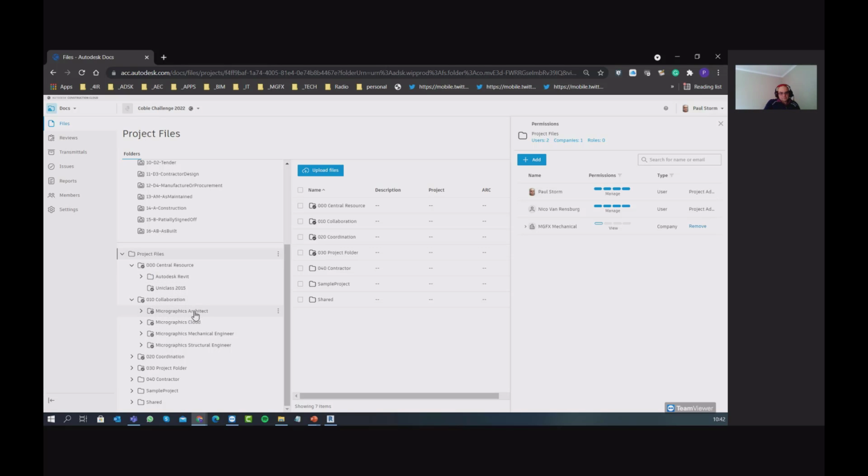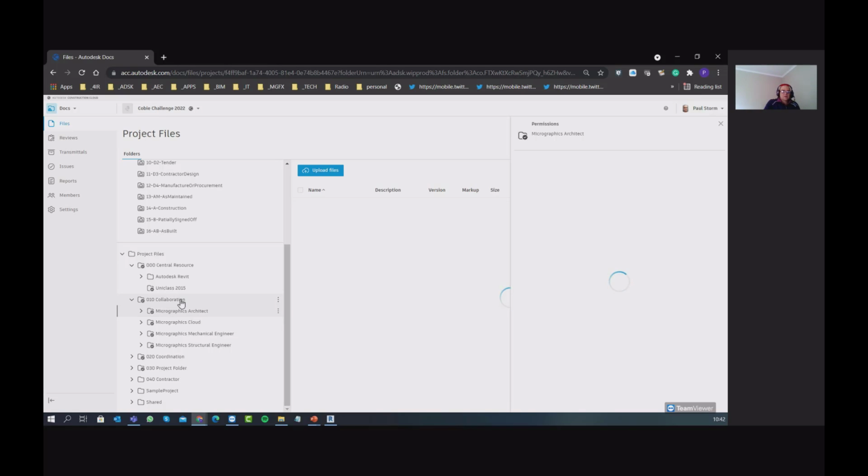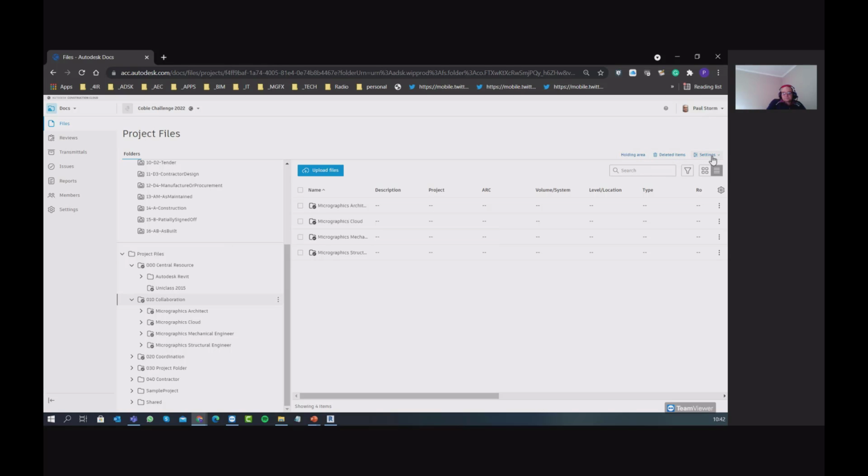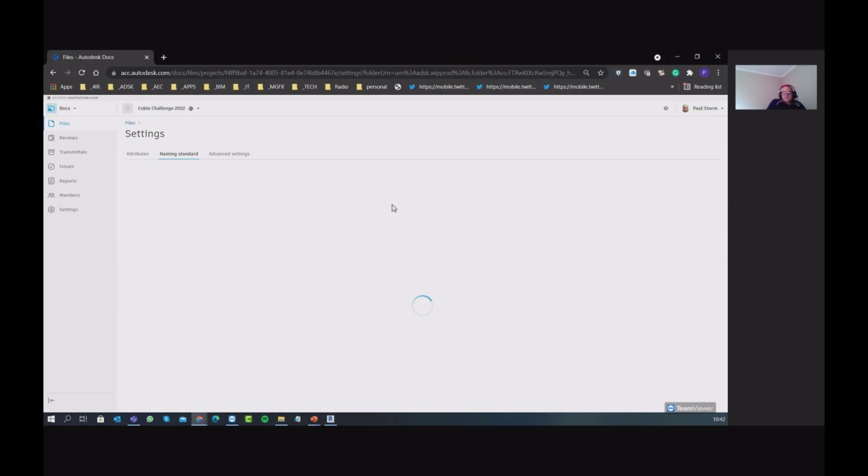In addition to that, which is nice now, is with most of the BIM platforms, we would like to have file naming conventions that are enforced. So with ISO 19650, that's something that came out recently, the BIM standard on ISO. They will apply a certain naming standard. So if you have a look over here on the enforced naming standard, it's switched on, then you'll be able to go to your naming standard.